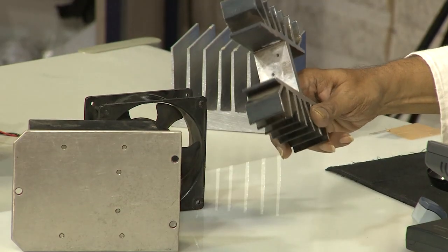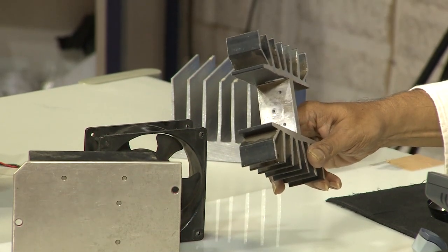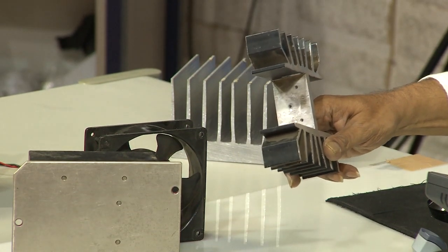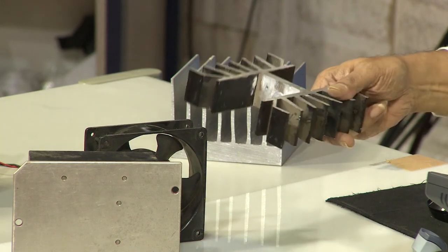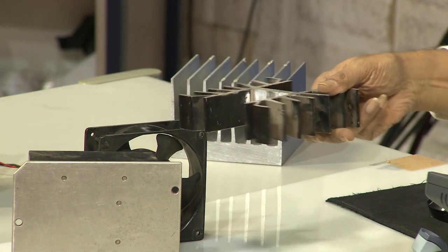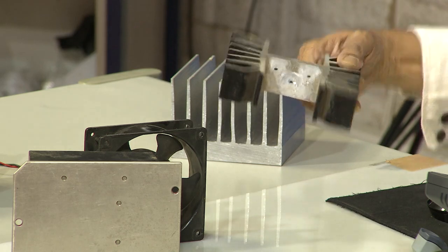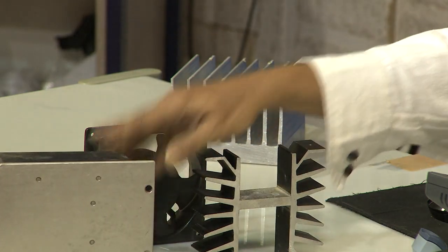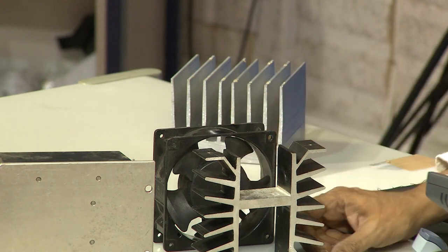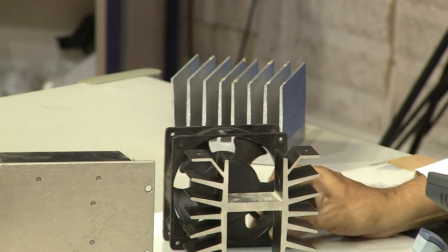These things are a compromise between how much space is available for your full module and what all you have to mount here. In this case actually it has been removed from where TO3 packages were mounted here, and this was checked for that purpose, saying if you just mount it as it is with the fins in the vertical direction, how does it work? Later on, can we add a fan directly, and what is the effect of this? If you have a thing like this, typically what is the effect?